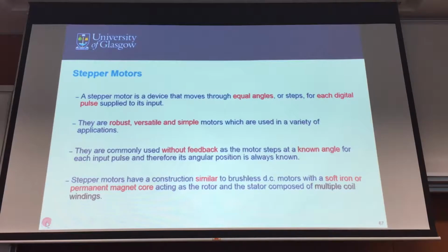You will have a certain amount of withstanding torque, but if your load is going to be very heavy, then it would kind of wind back. If it's very heavy, after you have supplied that amount of torque and still hold it in that position, it can only withstand this minimal amount of load, because the construction of a stepper motor is a brushless DC motor construction. Exactly. Brushless DC motor means that there's not much holding it except your magnetic forces. So if your magnetic force is strong, then you can hold it in that position stronger. Right.